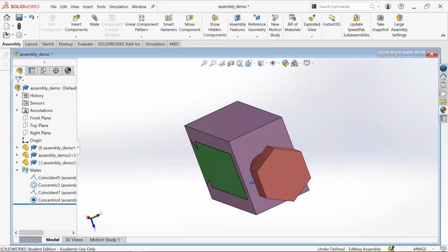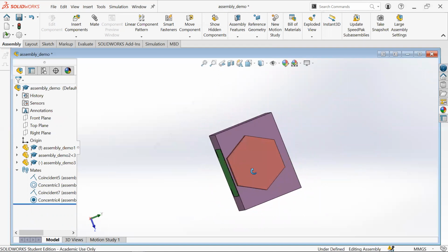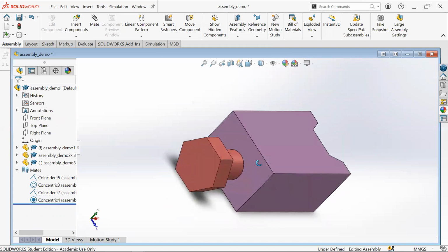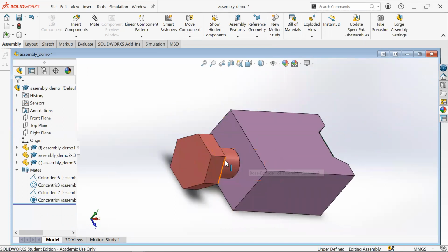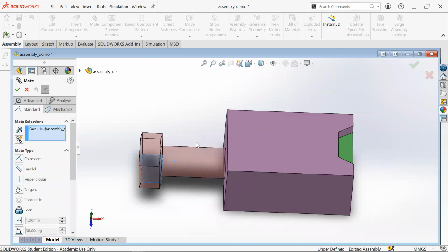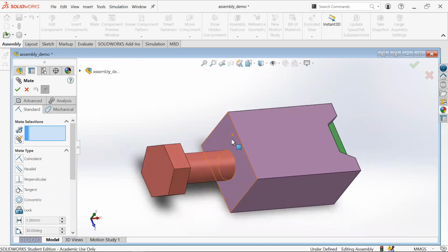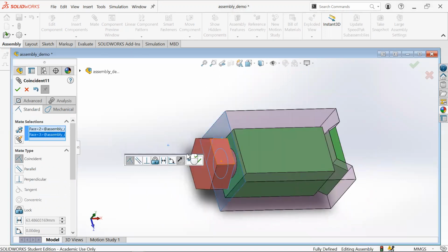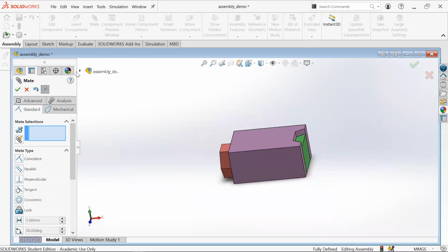And so to do that, you'll have to suppress multiple constraints, multiple mates. If you use redundant mates, for example, if you use too many mates, you'll have to find every single one of them and suppress them to get your part to be free in a certain way. So in this case, we're just missing one more mate, which is this inner surface. No, we don't want that face. This inner surface to this bolt inner surface. There we go.